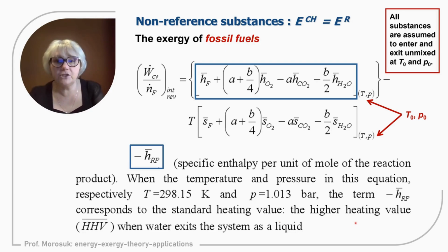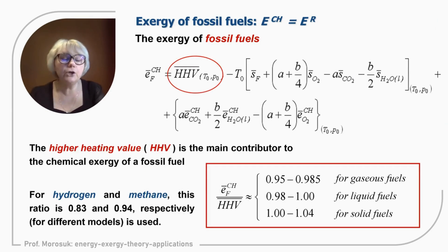But now we are with exergy analysis. And the standard heating value can be the lower heating value or the higher heating value, depending on which state the water is in. If water is in liquid form, then it will be the higher heating value. Therefore, this equation we can already rewrite using the higher heating value of the fuel. But the higher heating value of the fuel, this information is already available, or we can also calculate it ourselves.